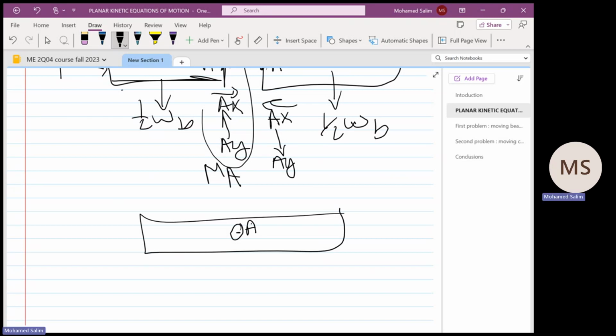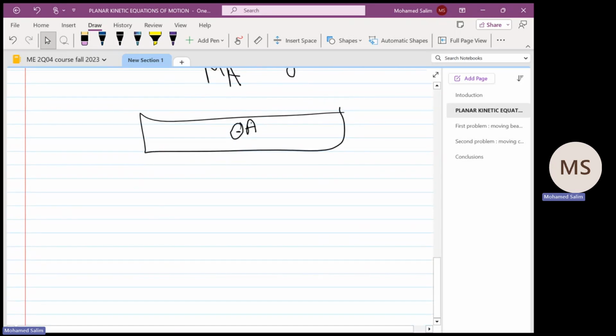My explanation here is just, I wanted to compare between the external forces and internal forces. Internal forces, again, are called reactions. And it's like a resistance to move or resistance to rotate. If you have a fixation point, you have two reactions in 2-dimension and 1 moment. If you have a pin and the body can rotate freely, we have only forces in x and y direction. Good.